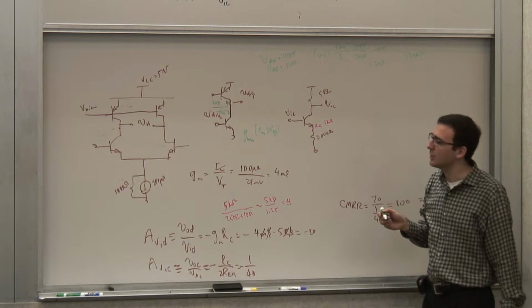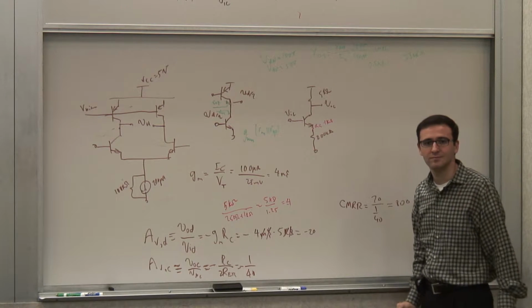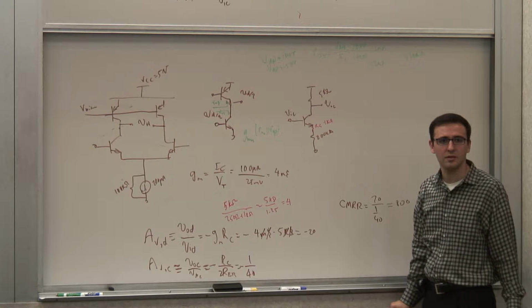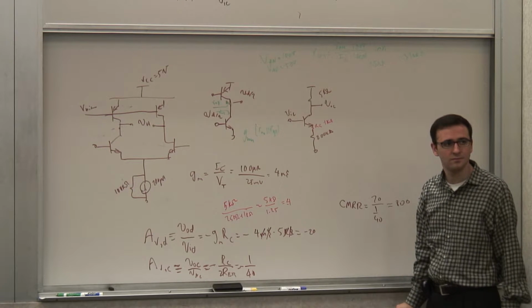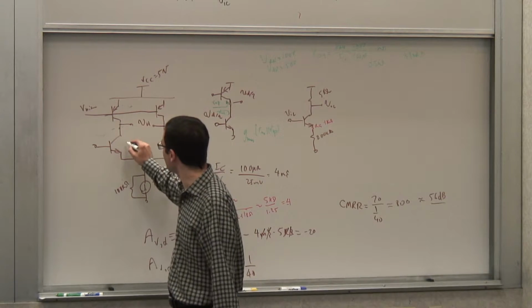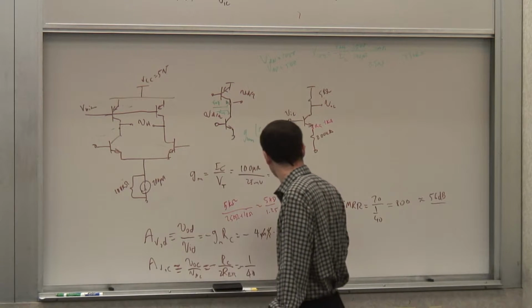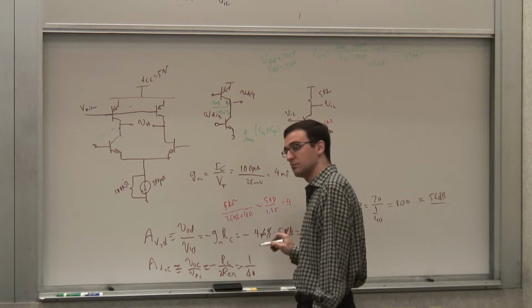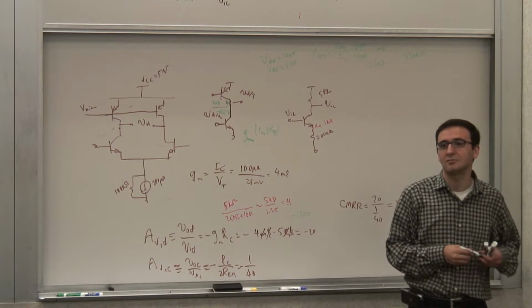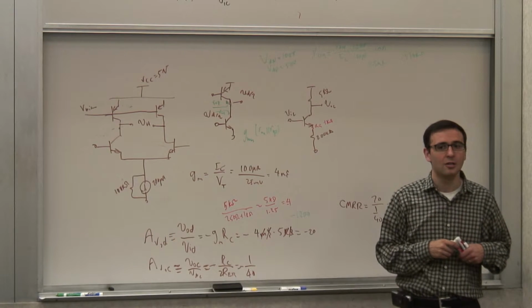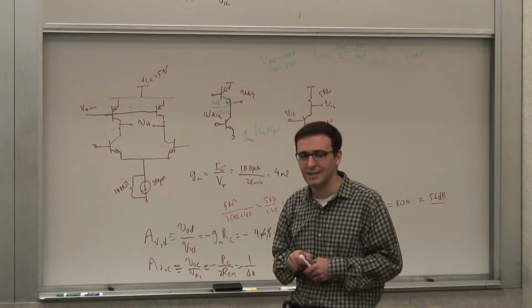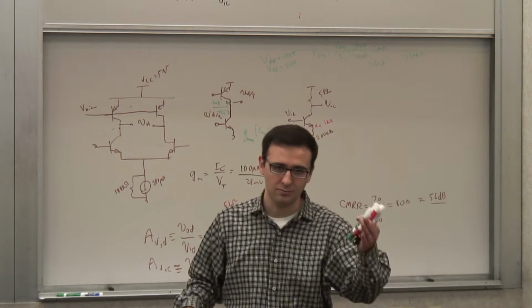So 330 kilo ohm times the 4 millisiemens. Kilo cancels milli. 4 times 330 is 1200. Ballpark. Right? So you get a gain of approximately AV of 1200. Much higher than 20. But of course now, let's say the gain is 1,000.